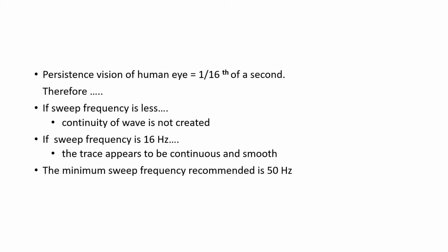The waveform observed in a CRO must be free from flicker. So, in order to get flicker-free waveforms, the sweep frequency generated by the horizontal sweep generator must be greater than the persistence of vision frequency of 16 Hz. It is better to have a sweep frequency greater than 25 Hz.